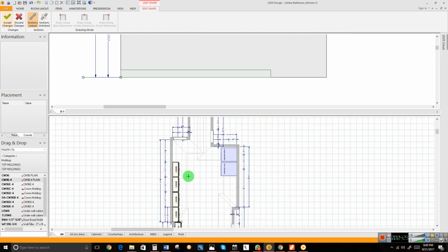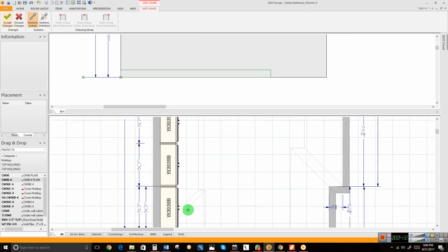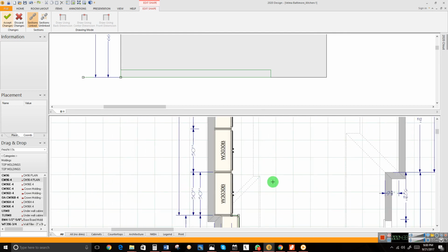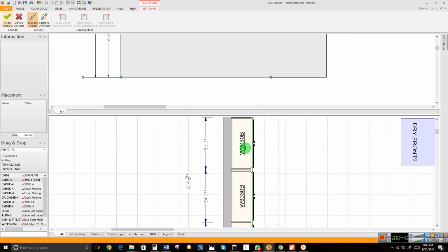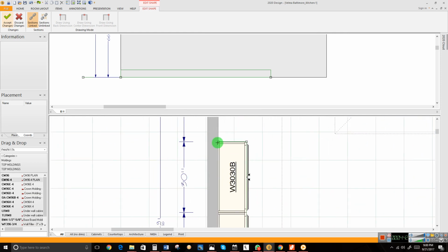Oh my, did I just delete everything? Well, luckily, I wouldn't suggest that, because this is probably what you should do. Delete it from point to point. Right-click at the point, make sure it's on the point, not on the line. Now you see that's a line, but move to the point and right-click there, it says point. Then select delete point. It deletes that.